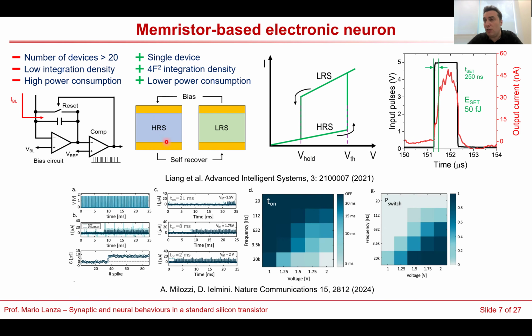So there are a few types of memristors in which the low resistive state is volatile. That is, when you apply the voltage, you can trigger the dielectric breakdown, but then this resistivity change is reversible. Whatever atomic modification of the structure of the insulator we have made, it self-recovers when we switch off the voltage.